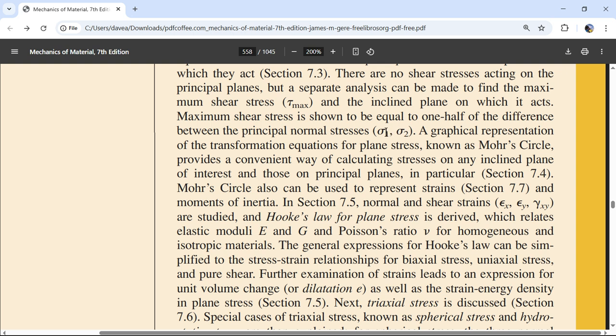Now that's not quite true, because if we have axial tension and we are also compressing the thing, this would be negative. So we have a positive and a negative, and the difference between them is a positive minus a negative, and our shear stress is half of that. So if we're pulling apart a chunk of steel and also squishing it in a vise, we can get it to shear on that 45 much easier. That would be an interesting thing to see in a lab, but that's kind of what that's saying in a nutshell.